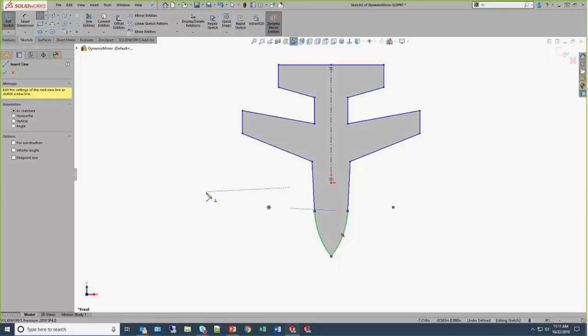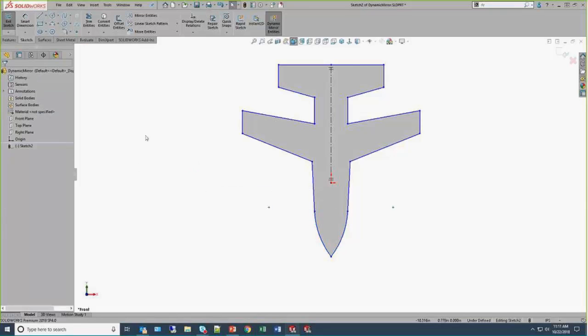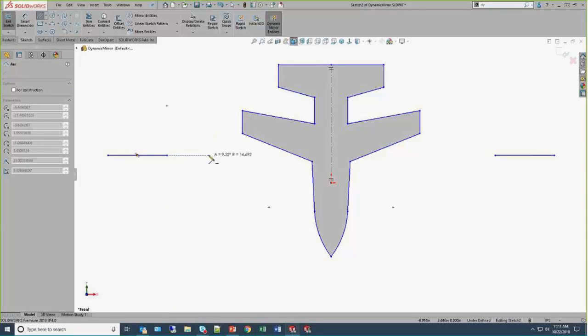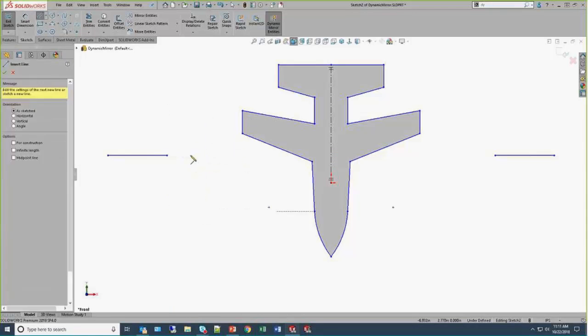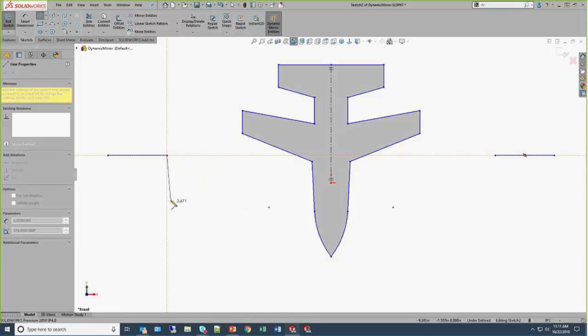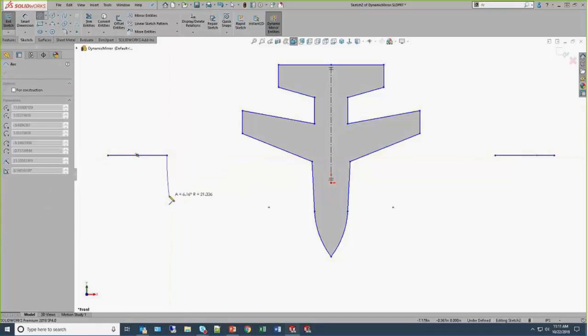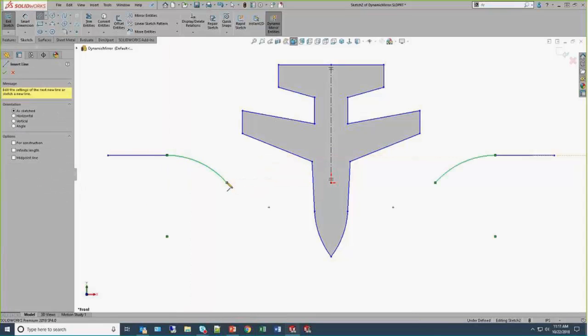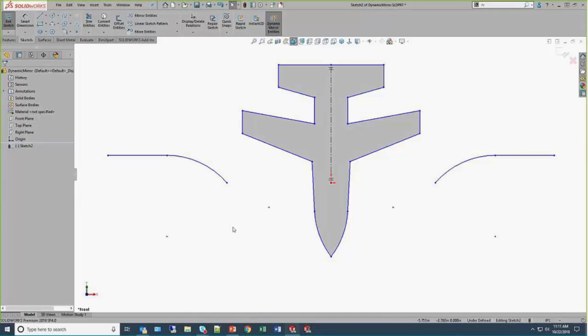So again, when you're sketching a line, I'll show it over on the side just for another example. Click mouse, click, and you can see I have dynamic mirror still enabled. But if I hit the A key, it'll switch over to a tangent arc, hit the A key again, switches to a line. If I come more in the perpendicular direction, you'll see the other possible solution there. So a really handy way to just jump between lines and arcs.